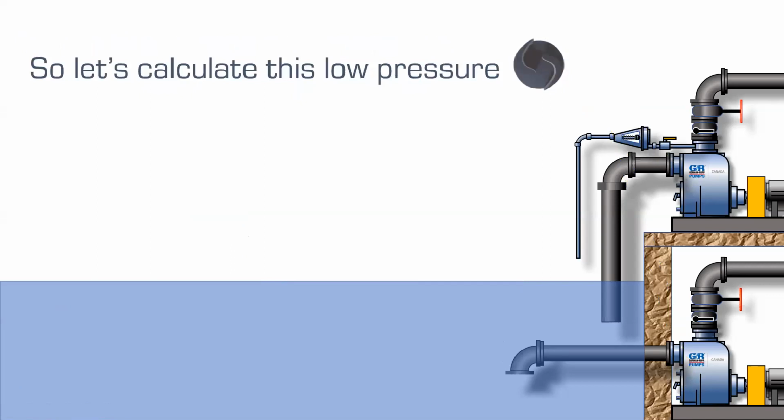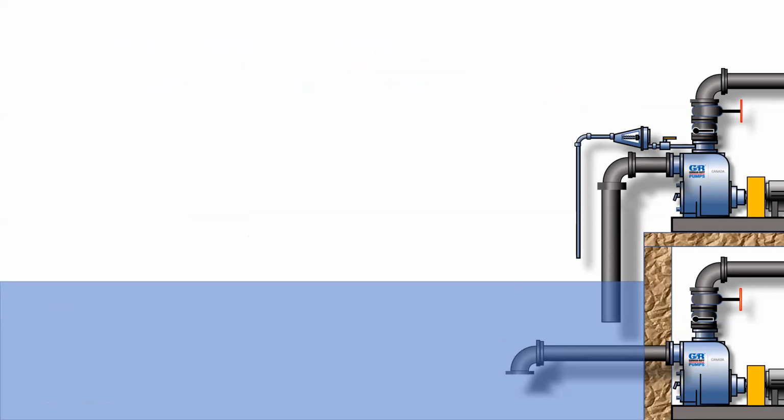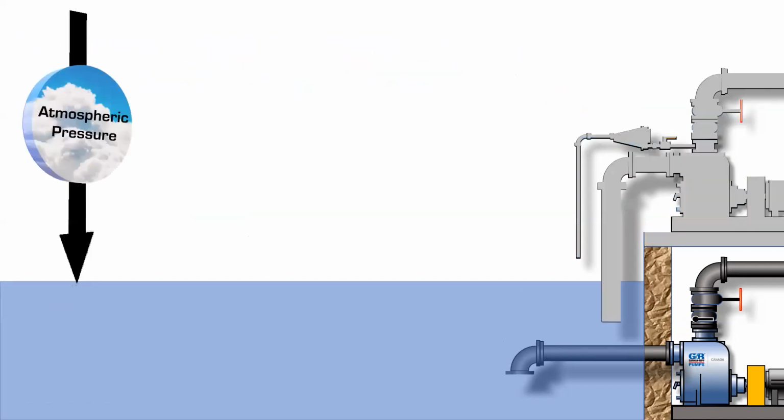So the right answer is going to be the eye of the impeller. That's what's really generating this flow on the suction side. So it better be the low pressure zone, okay? So what we want to do now is go through a calculation involving what is the actual vacuum draw at the eye of that impeller.